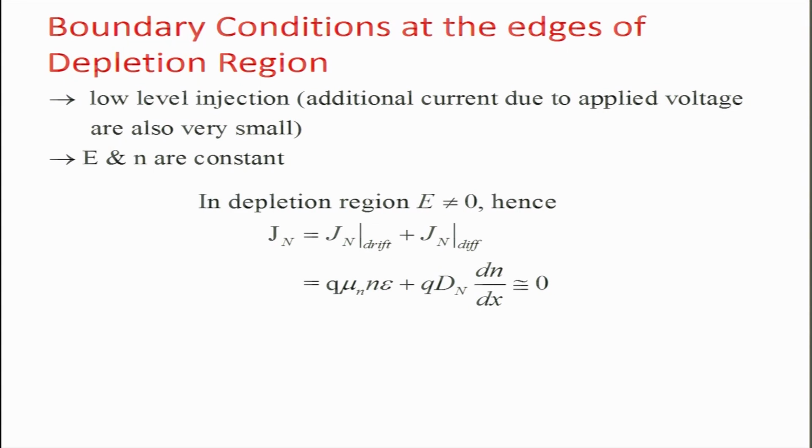So the drift current is going to be equal to q n mu n E. This is E, the electric field. I have noted this because there is a confusion between E as electric field and energy. So, you can say that this is the electric field. We know from Ohm's law that J is equal to sigma E, which is equal to n e mu E.